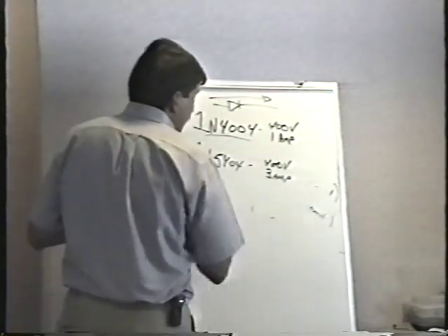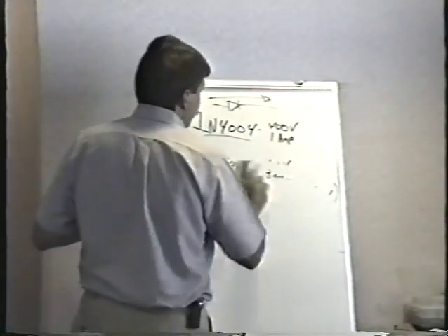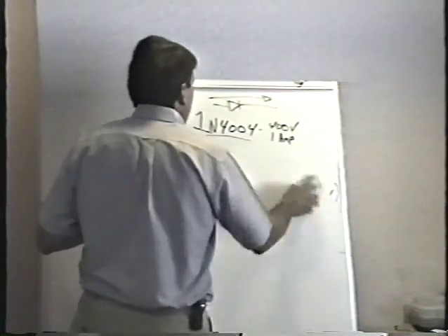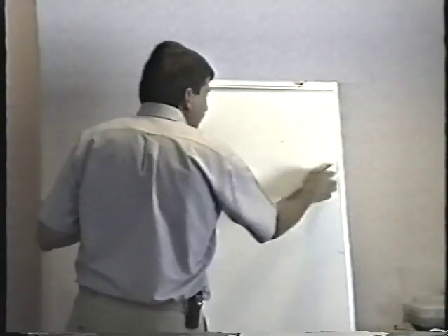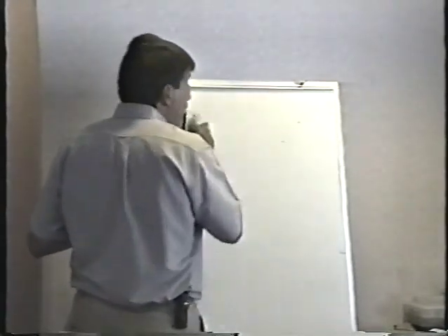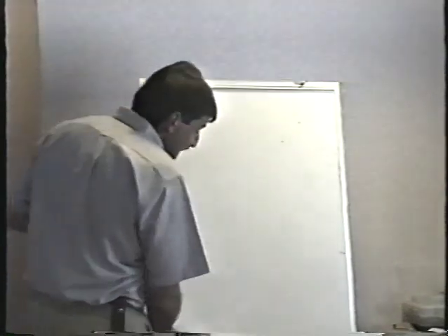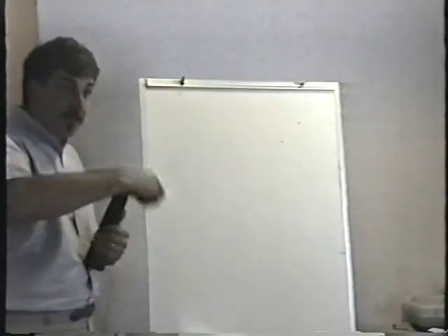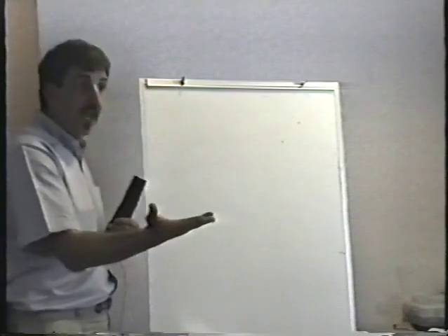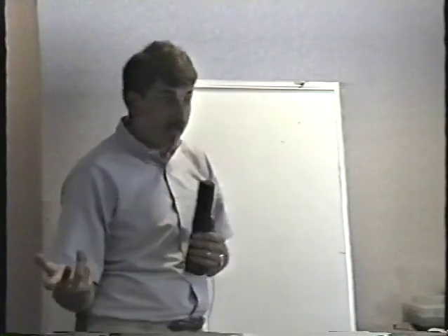Diodes, there's no question at all about checking diodes. Like I said, most of the time you can test them in circuit. Generally, my philosophy regarding checking parts in circuit, that is, as they're mounted on the boards themselves, is that I always try checking everything in circuit first. If it seems like it's bad, you're going to take it out to replace it. When you get it out, double check it. When in doubt, pull it out. If you're checking a part in circuit and it checks a little weird, and you don't know what's going on, unsolder it, take it out of circuit.